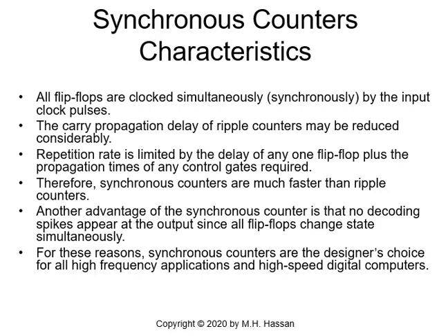Another advantage of the synchronous counter is that no decoding spikes appear at the output, since all flip-flops change state at the same time, simultaneously. For these reasons, synchronous counters are the designer's choice for all high-frequency applications and high-speed digital computers. When you work in gigahertz, synchronous counters are a must choice.